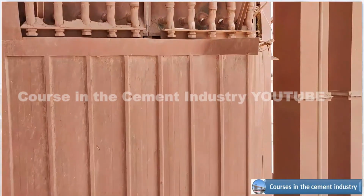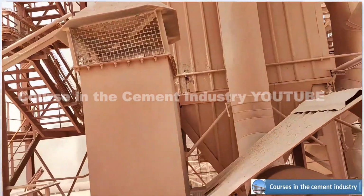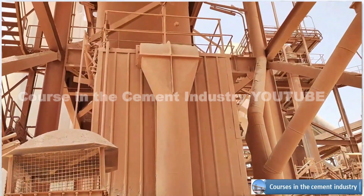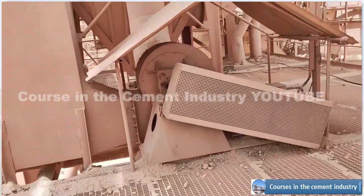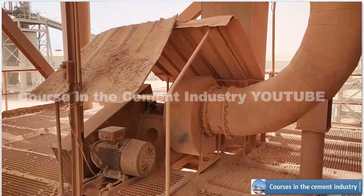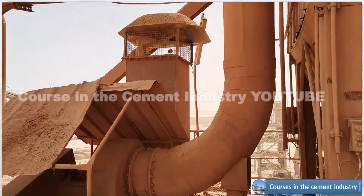The filter is operated cyclically, alternating between relatively long periods of filtering and short periods of cleaning. During cleaning, dust that has accumulated on the bags is removed from the fabric surface and deposited in a hopper for disposal.